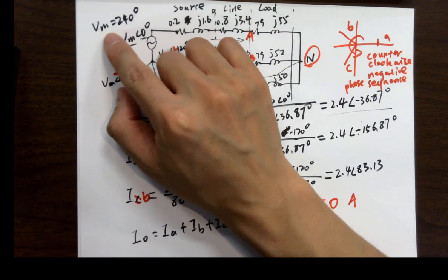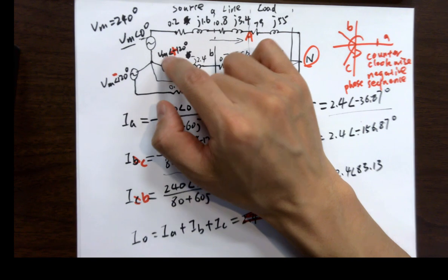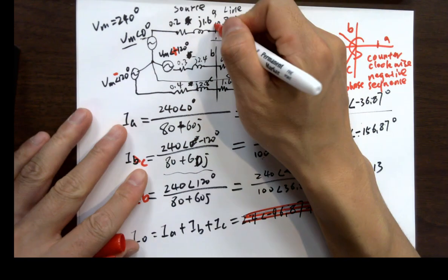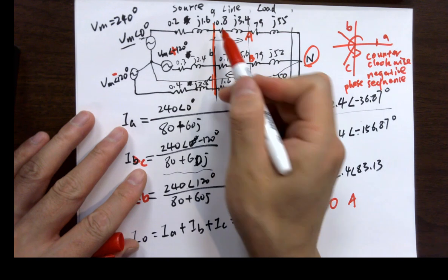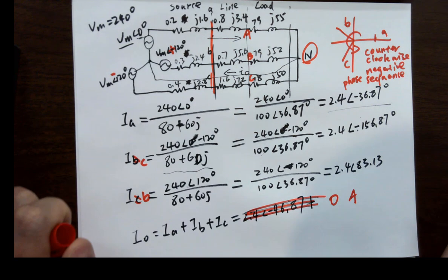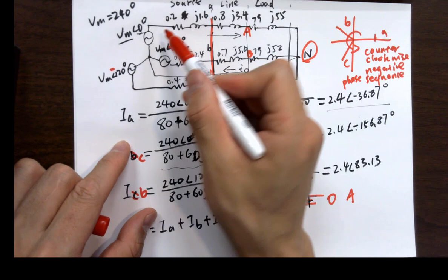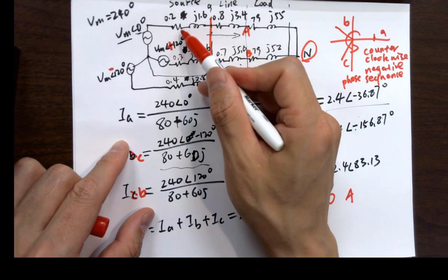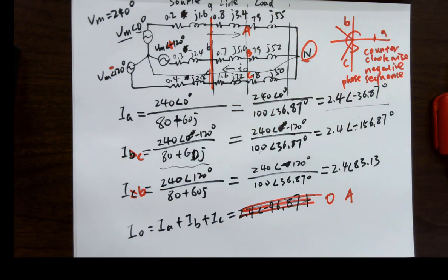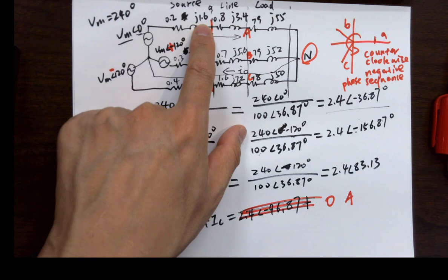Now here, same magnitude and 120 degrees apart, perfect, balanced. It won't be balanced if you look at this terminal as a source terminal, because those are the real source terminals you are using to drive the line and the load at the same time. The impedances are not the same, so it's causing different phase shift, okay? If you look at this, see, this is 0.2 plus j1.6,